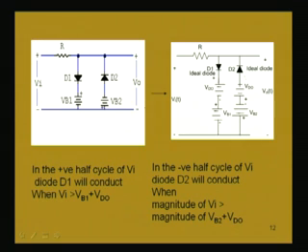Similarly, the other diode conduction is in this direction from bottom to top. So, the diode drop Vd naught will also have the same polarity, that is positive here, negative here. This is Vd naught, and the other voltages, batteries Vb1 and Vb2, are as we have drawn, and these are ideal diodes. So, we are now to find out what is the output voltage for a given sinusoidal voltage Vi(t).